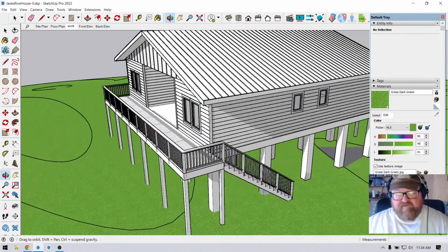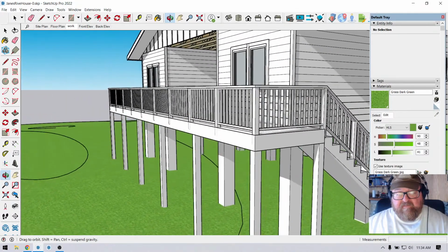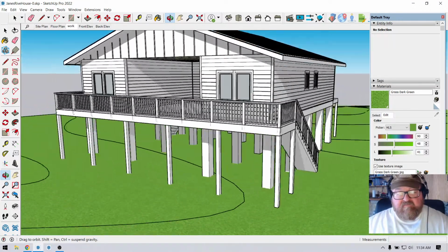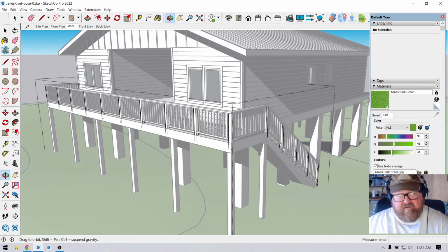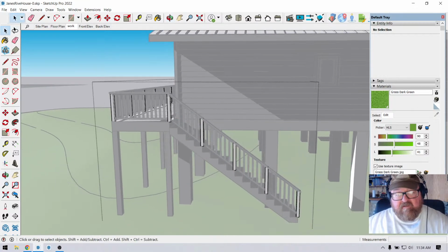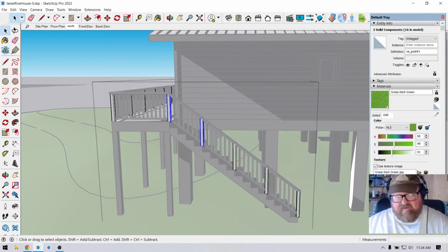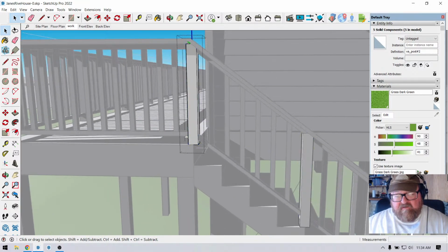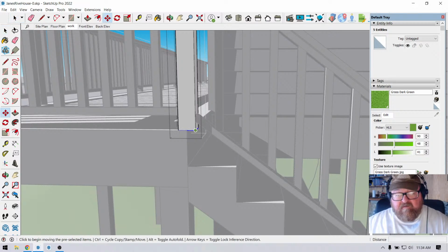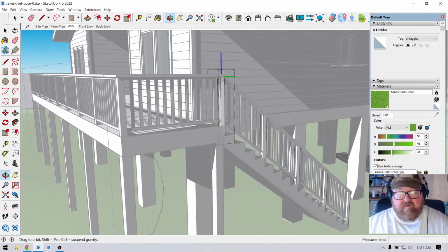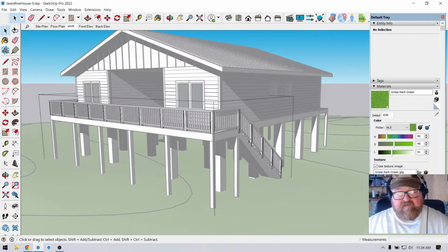Okay, so he made those components, so they all went down. And for the purposes of this drawing, that's good enough. Except that those went down too. So let's undo that. And what we will do is we should be able to make these unique right here. This will be a little trick you can learn for SketchUp. Make unique. That means now only those will go down now. So those went down and these didn't. Okay, thank you, Jesus. There we go.